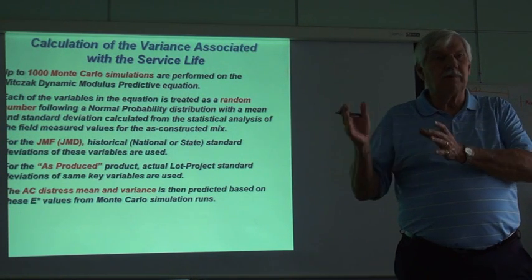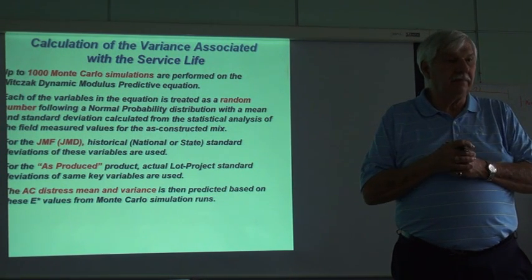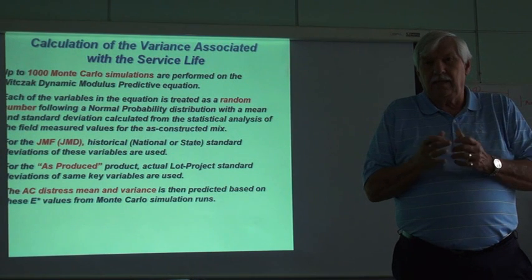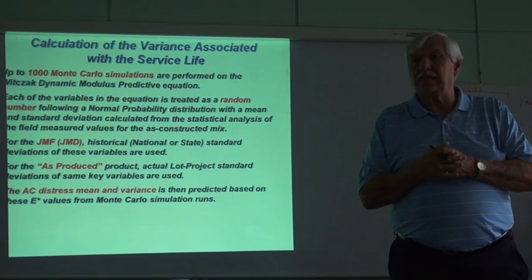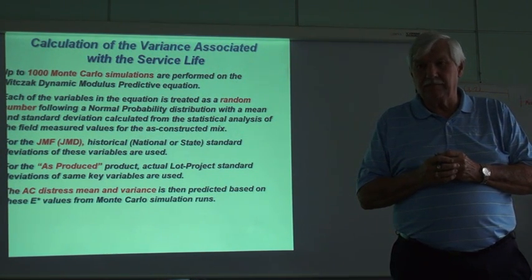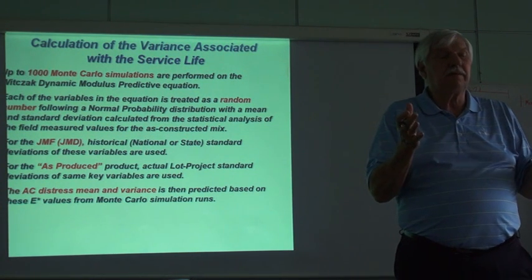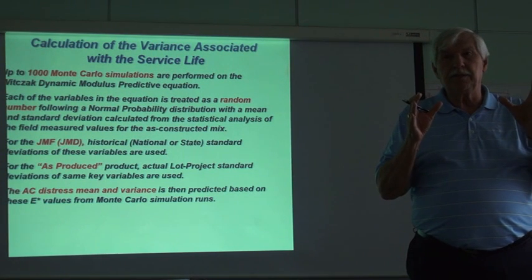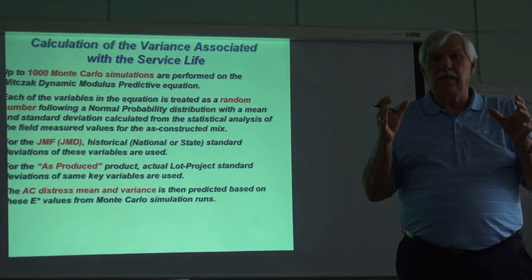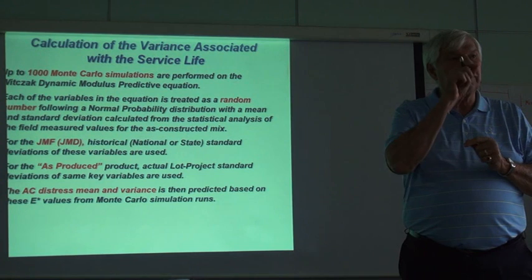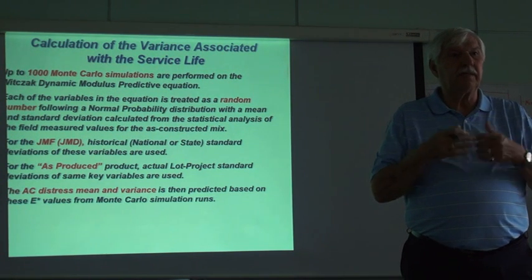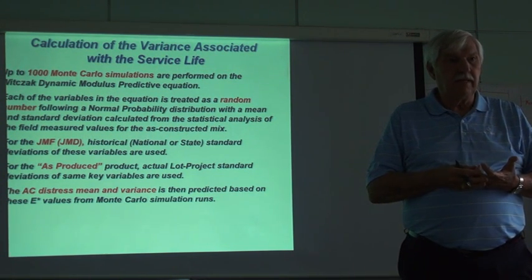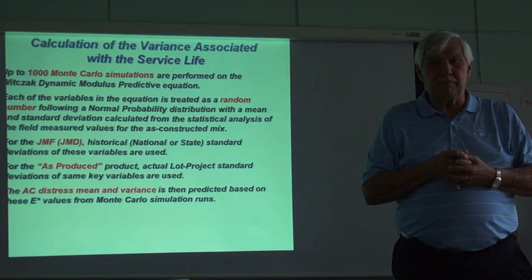And a lot is whatever you want to conveniently define as a lot. In the agency, it may be 1 day's production of a hot mix plant, or it may be 2,000 tons production. But what you're going to do is take a lot, and you're going to sub that up into statistical sampling areas we call sublots.